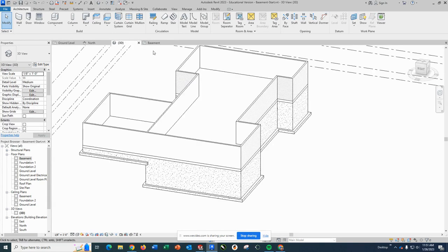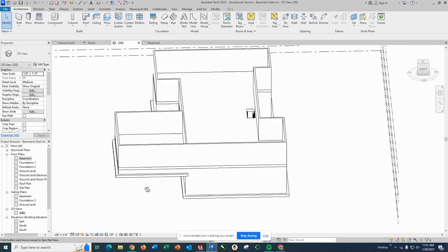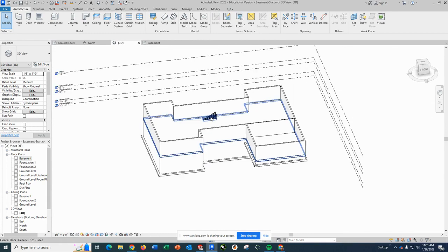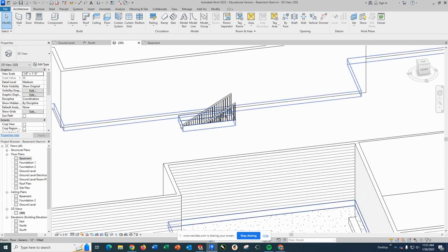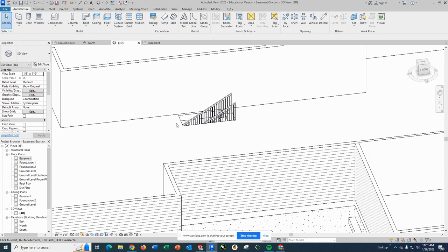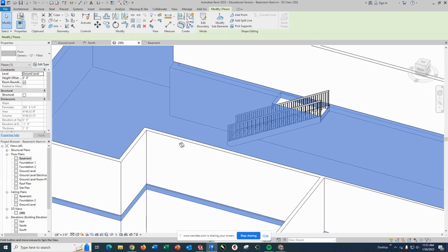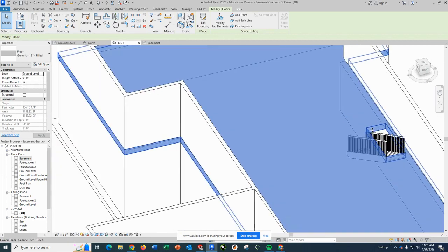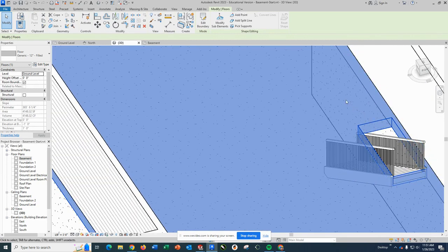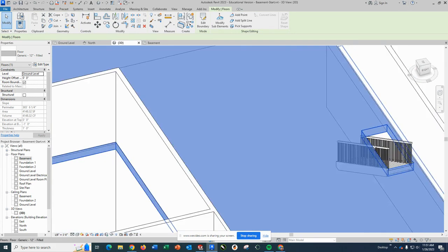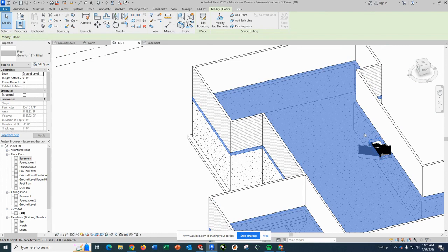Looking at it from a 3D view, I can turn this and you can see my staircase now comes up through the floor. Now you can change this a little bit because if you look at the way this is, the nice part is you can click on the floor and it kind of shows you a hollow view. I really need to actually take this back quite a bit more because as you can see, everybody hit their head walking up these staircases unless you're like 3.5 feet tall. So you can actually take that back a little bit further to cut that hole in the floor.